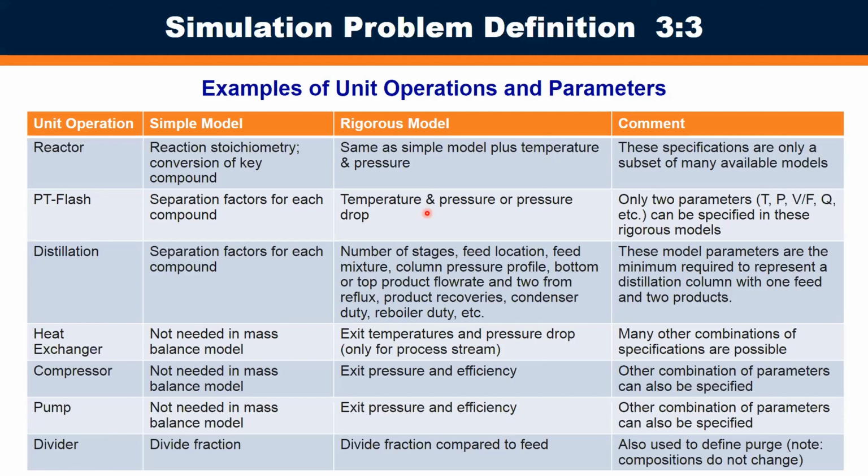If you're solving this in a classic forward manner, what you would do is you would iteratively set the conditions, temperature and pressure for the flash, and evaluate the outlet streams. But because the simulator solves the same set of equations regardless of which parameters you specify, it's much more effective to specify the desired split that you're looking for and have the simulator calculate the missing variable, which could be the energy requirement or the temperature needed or the pressure needed.